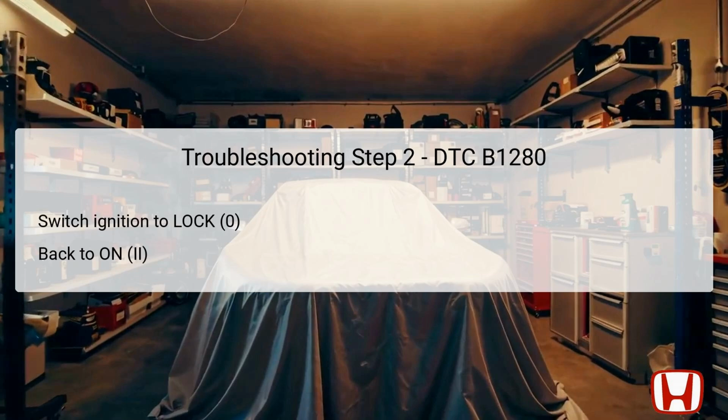In the second step, ensure the ignition switch is turned to the lock 0 position and then back to the on 2 position. This sequence helps reset the vehicle's electronic systems, allowing for accurate readings during diagnostics. Operating the ignition switch this way prepares the vehicle for checking the turn signal switch's functionality. It's essential to give the system a moment to stabilize after this sequence before proceeding to the next steps in the diagnostic process. Ignition system resets can help clear temporary faults that might interfere with operational checks.